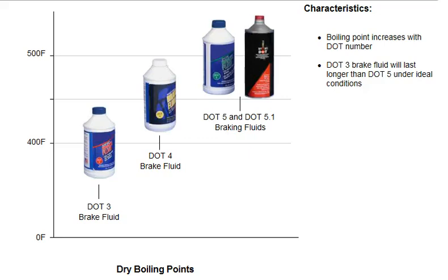Currently, higher DOT numbers indicate higher boiling points. Under ideal conditions, meaning a clean, sealed system, the lower numbered brake fluids last longer.